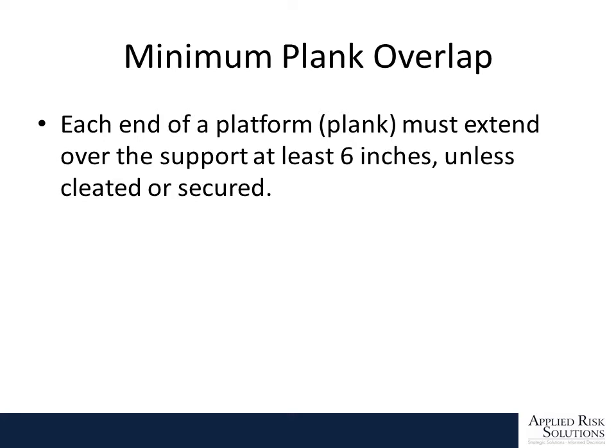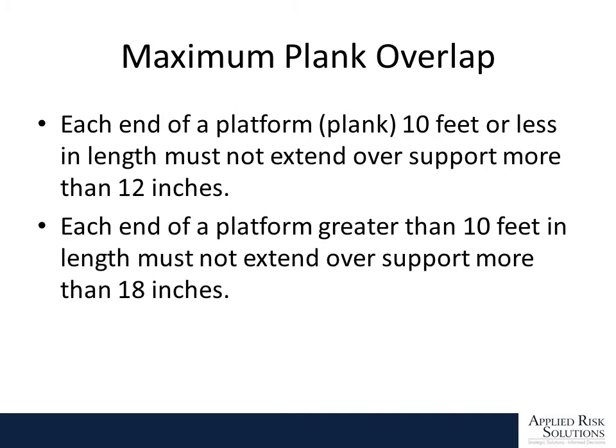The minimum plank overlap is 6 inches, unless you're cleated and secured. The maximum overlap, if the board is 10 feet long, is 12 inches. If the board is longer than 10 feet long, you can overlap up to 18 inches.